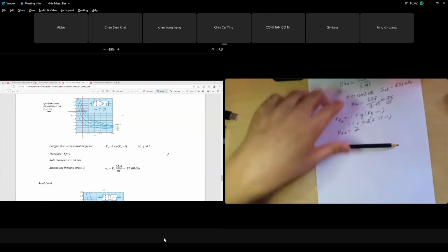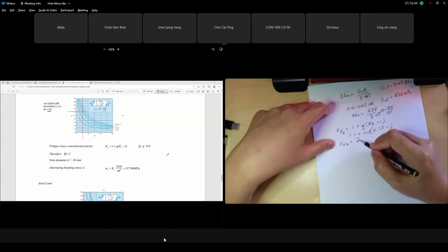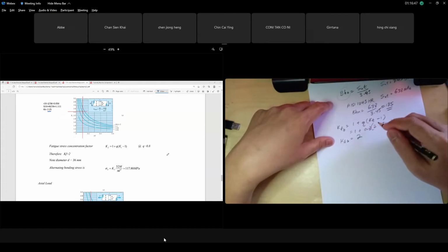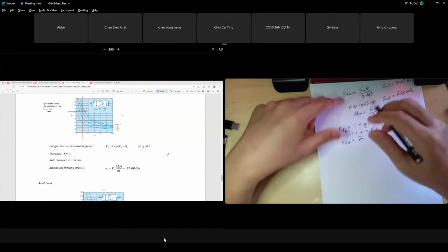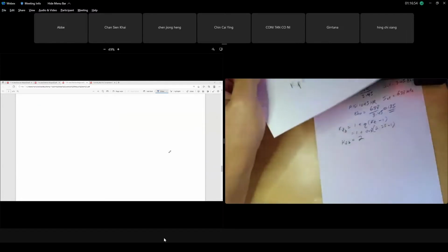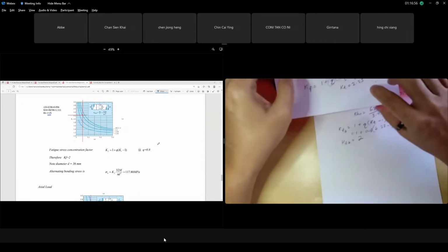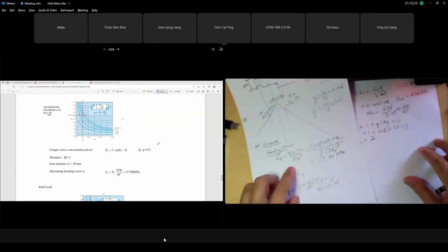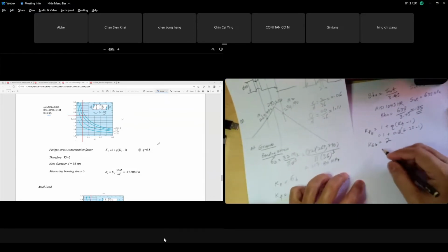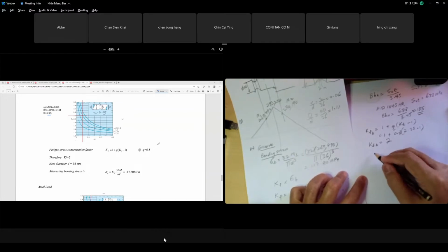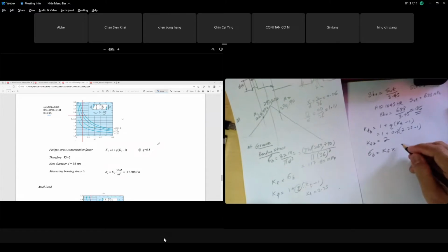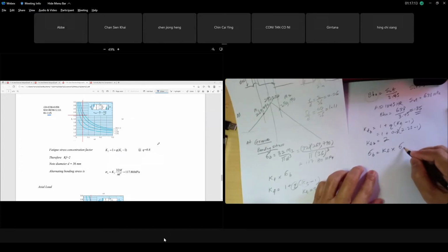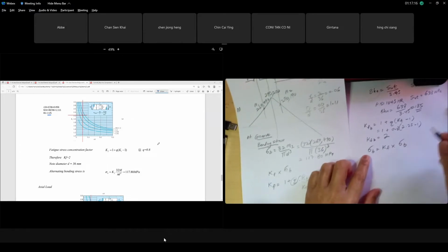Sorry, the line was cut off. Okay, so we have our KF bending equal to 2. This KF bending has to be multiplied by your bending stress from just now. Remember your bending stress at the groove? So you have to multiply KF times your bending stress, sigma bending. This one has to be multiplied by this one.